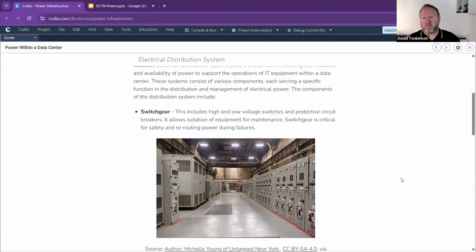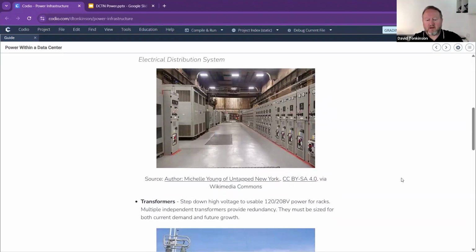But you'd normally expect to be able to not just shut down an entire room in a data center, you'd also expect to be able to shut down an entire row of server racks. And that would normally be on its own switch center. In fact, it would probably be on 2 switch centers from 2 separate switch gears. So you would have 2 power systems running to that rack, that line of racks anyway. And it allows us to safely do this without any issues.